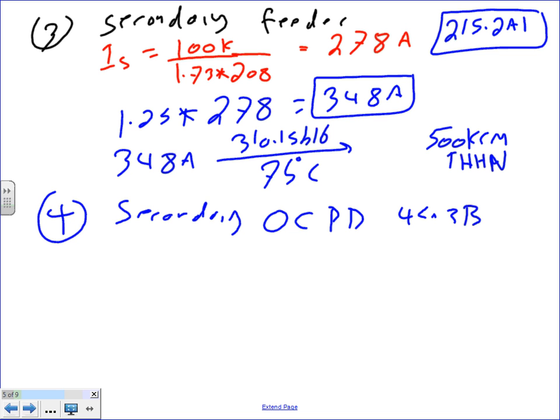Should I derate the neutral? If we're going to derate the neutral, we have to land it on the panel and we do the calculation slightly different. In this case, I'm going to pull a full neutral. So how many conductors then? 4 conductors. Could I have taken this neutral and derated it based on a 200 amp? Yep, I could have derated the neutral.